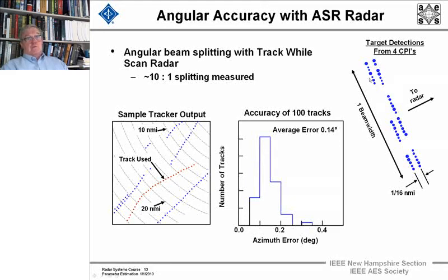It's seen in both. So when we're calculating the range, you can take a weighted average of the range, weighted on the amplitude, to get the exact range that we'll put into this. And this is called consolidation and interpolation, is the process that's used. And we'll talk about that later when we go into tracking and in detail the tracking process. But this consolidation goes into giving you one of these dots.